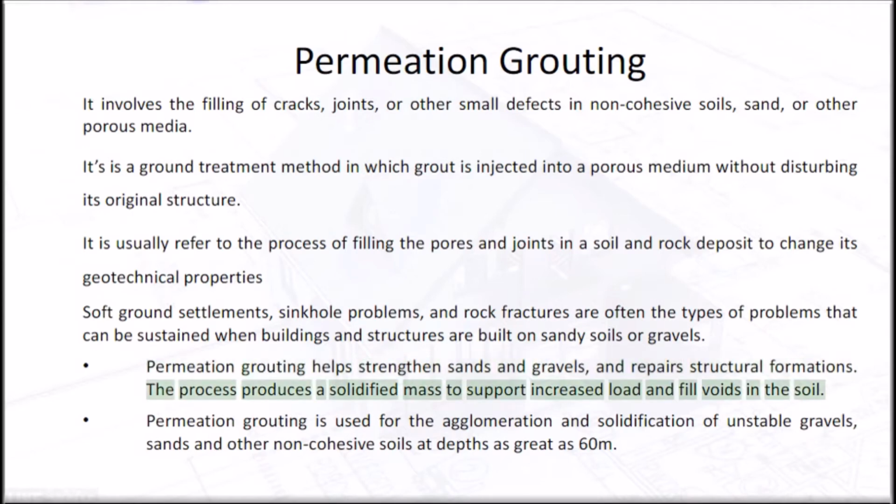The process produces a solidified mass to support increased load and fill voids in the soil. Permeation grouting is used for the agglomeration and solidification of unstable gravels, sands, and other non-cohesive soils at depths as great as 60 m.